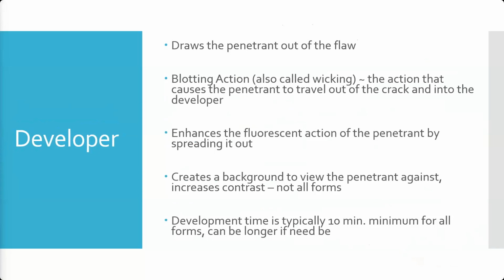So it's important that after the inspection's done, you clean this stuff off so that it doesn't leave a residue on the part. In addition to that, some of it does work its way into the cracks. If it dries in the cracks, it can actually clog a crack. And then the next time somebody inspects the part, the crack gets smaller. You have the same concern with dye, so dye or developer getting into those flaws, right? Especially if it's a flaw you're monitoring over time where there's a certain amount of allowed damage and you're making sure it's not growing too fast or that it hasn't grown too large. It's really suspicious when you measure a crack today that's 1.5 inches long, and then you come back a month from now and that crack is 3/4 of an inch long.